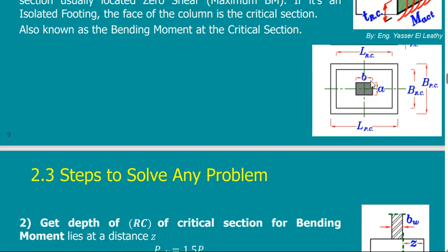Suppose you did not do this, it's not important, but if you have different cantilevers, then you will have to design each cantilever and get the moment. If I use this approach, then I don't have to design except one cantilever, because the value of the moment here is equal to there, is equal to here, is equal to there.